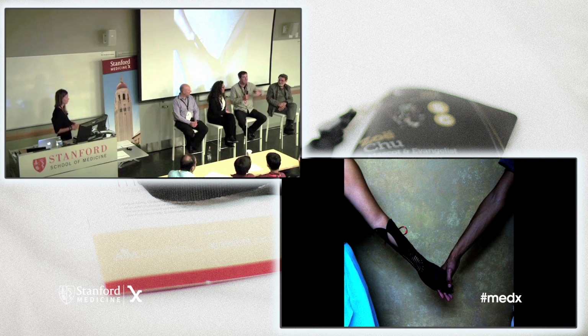But looking ahead, and this is where things get exciting with 3D printing, we're getting into this world now of what we call digital materials. And that is an entirely new thing. That is a break in the continuum of fabrication of anything, because now you can print simultaneously polymer and elastomer in a dithered way. So for example, you can have something that is as squishy as a gummy bear, imagine a ruler, as squishy as a gummy bear on one end and as hard as solid plastic on the other, with a linear gradient between the two. Impossible any other way. Or a nonlinear gradient.